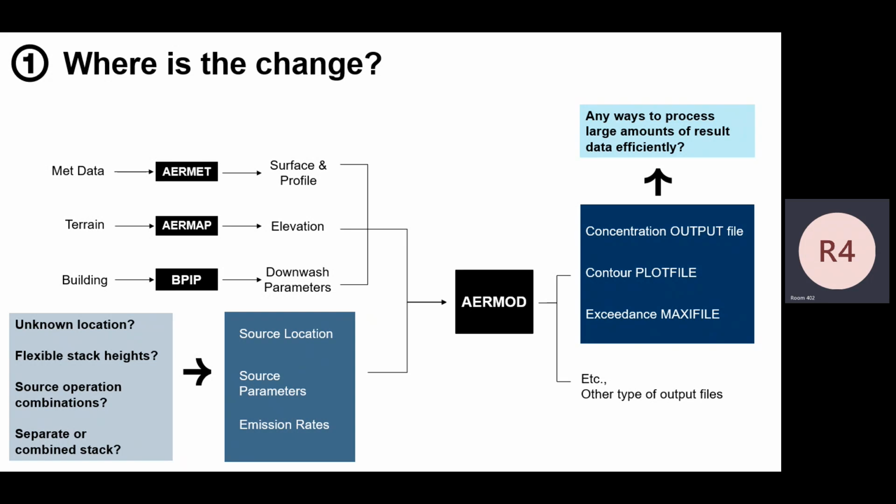When you run this model for your pollutant, say by a 1-hour standard, it can tell you how many times it exceeded the threshold you set for it. This is very useful when doing air toxics health effects reviews, and there are all the other output files. That's the AERMOD, and we have done nothing yet.